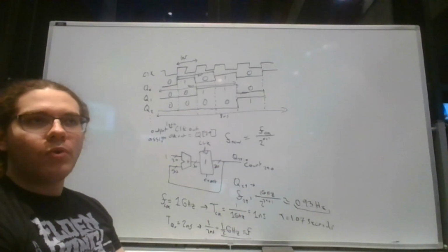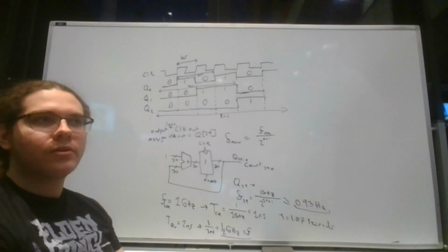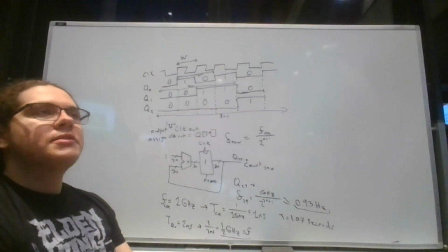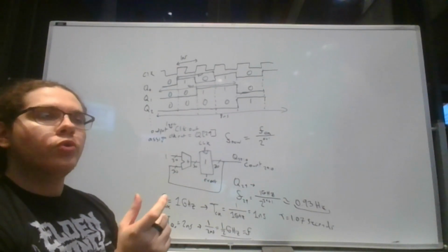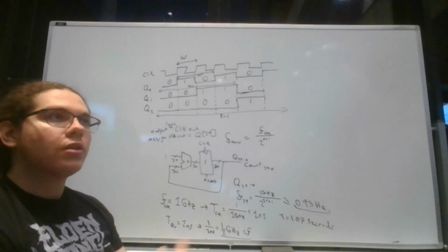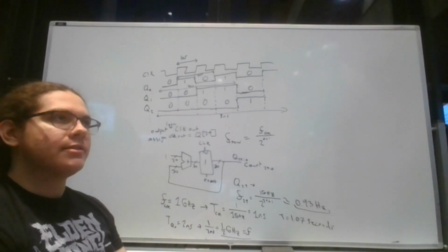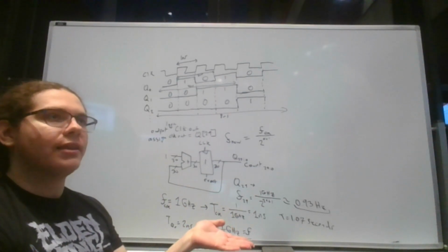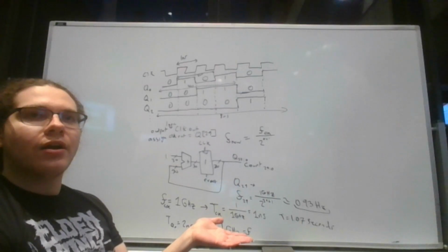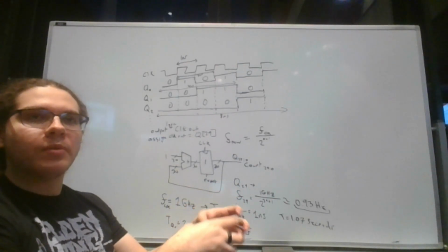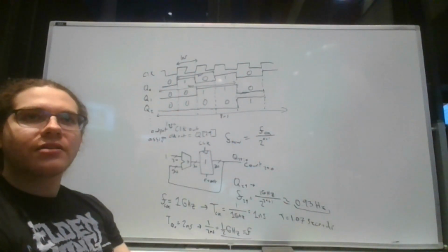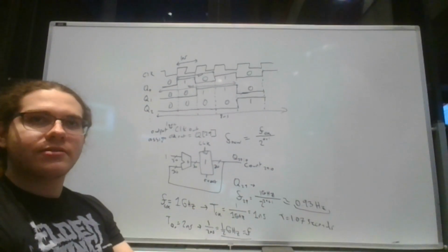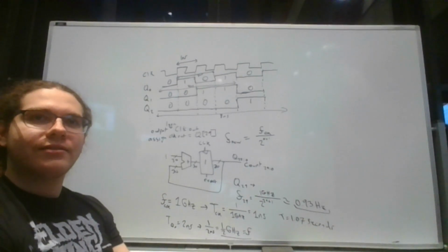When you have a desktop or any computer, any system, the people who designed it typically leave a little bit of wiggle room in terms of how quickly you can run your clock. They don't want to send out a system that works fine for some people, and then other people who live in harsher parts of the world can't use it because the clock's too fast, and you get hold time and setup time constraints that are violated. Right, you violate them.